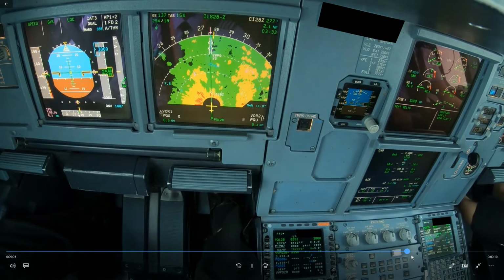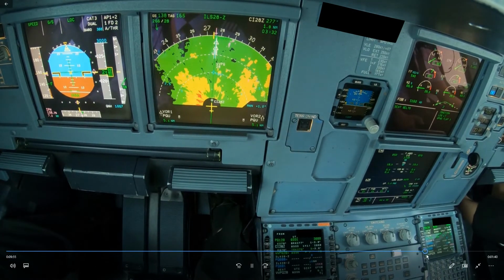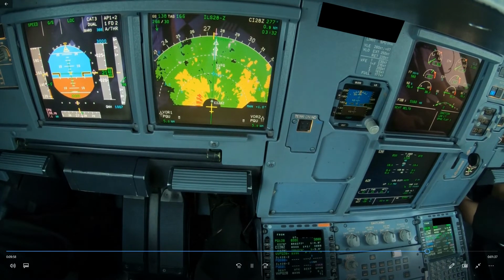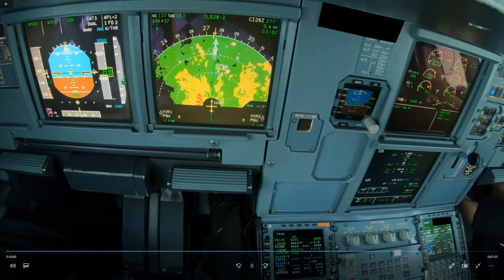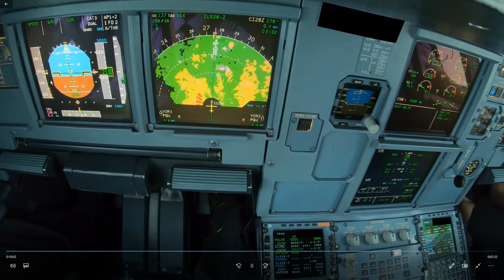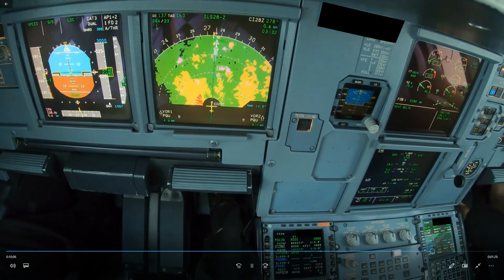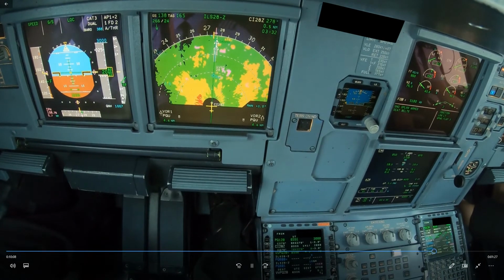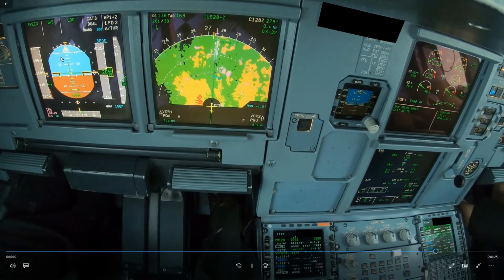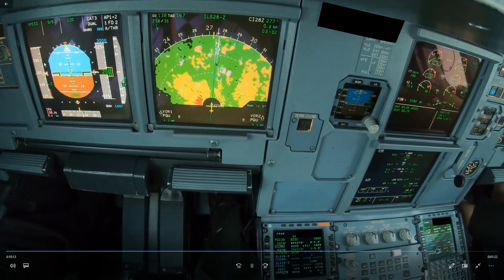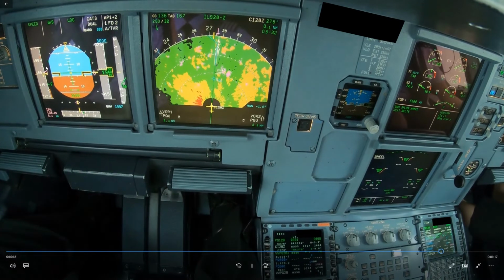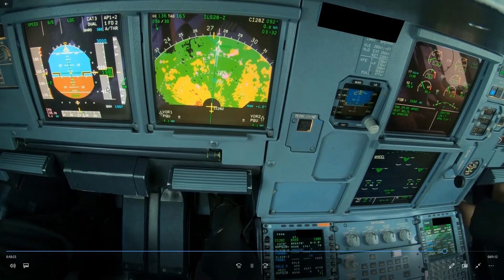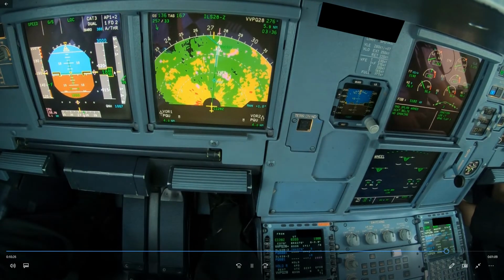So let me skip ahead a little bit. So there we are approaching 2,000 feet. You can see the speed increasing here, this is actually ground speed mini due to the headwind here. So there's 2,000 feet, we lower the gear. Now next, when to select flap. If you are very fast, you want to select flap without delay. As soon as you are 5 or 10 knots below VFE next, depending on the turbulence, you want to select the next flap stage. But if the speed is on the low side, you can wait until not lower than 1,800 feet to select the next flap stage.